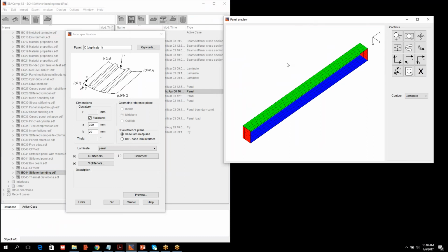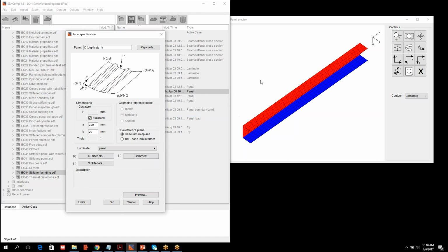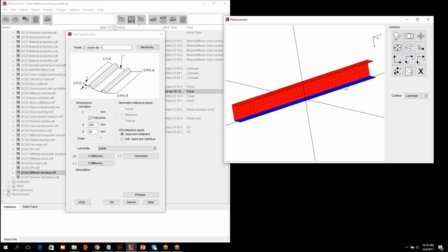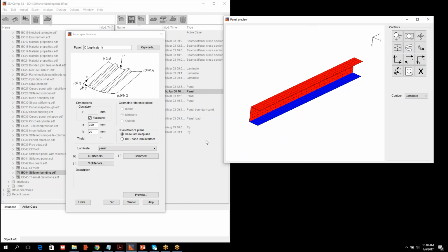the stiffened panel. What I do first is remove these rib stiffeners from the ends, so they are Y stiffeners. First, the farmost, I will pick it and delete it, and the second one. And now we have only the longitudinal stiffener attached to the panel.